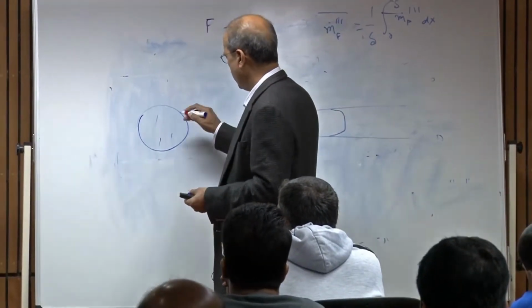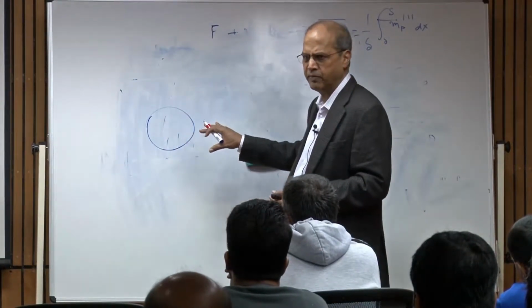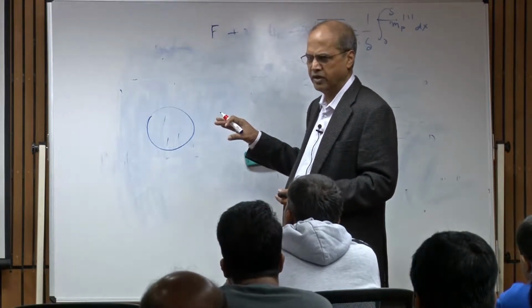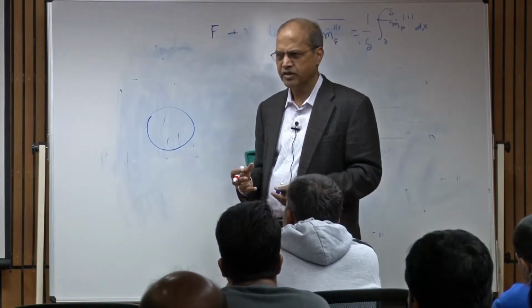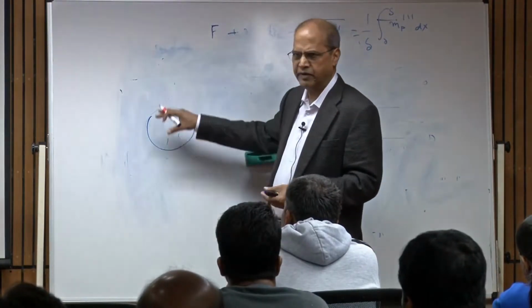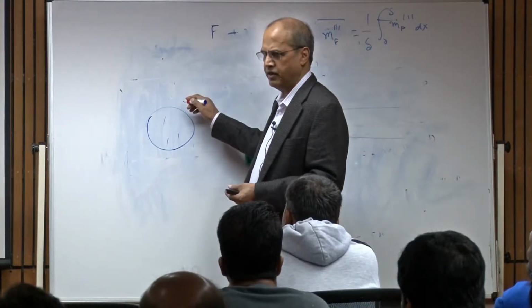When you ignite it initially, there are 2 ways. You can have this droplet injected into a hot environment, so it's like auto ignition. The ambient temperature of the environment is high enough, so the vaporization will start.